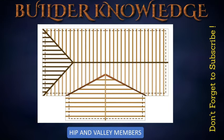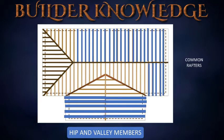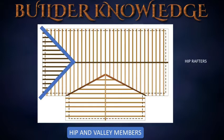Hip and valley roof framing members. The ridgeboard is the same as in a gable roof. Common rafters are the same as in a gable roof. And collar ties are the same. What is not the same? Hip rafters. They extend diagonally from the outside corner formed by perpendicular top plates to the ridge board.